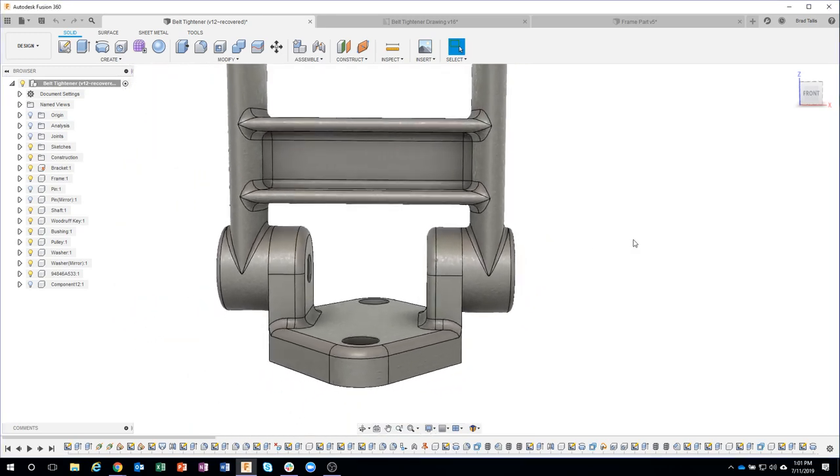And again, we're giving you methods and ideas on how you can design, but when you go to manufacture this, you have to have the experience and the knowledge on how this is going to be manufactured. Typically people will use tolerance blocks on their drawings. When they've dimensioned their drawings, they might have a tolerance block in the corner that says any dimension with 1 decimal place might have a tolerance of 5 thousandths. Any dimension at 2 decimal places might be 2 thousandths or something like that.